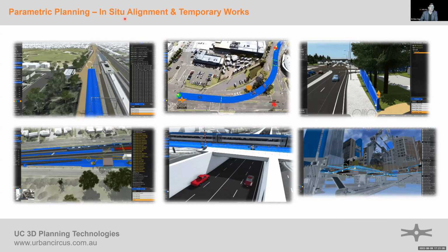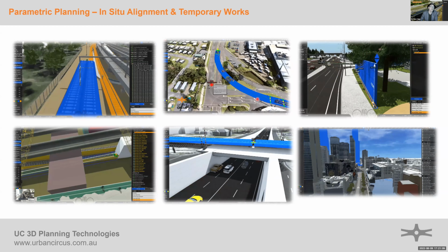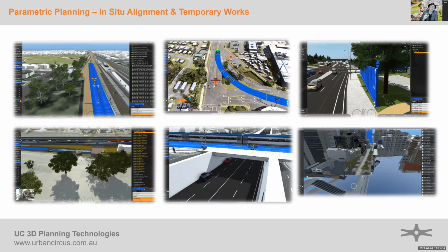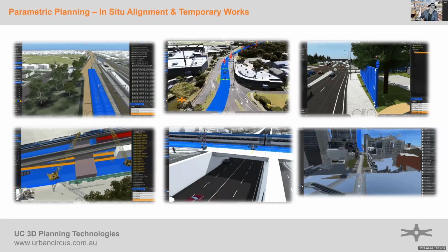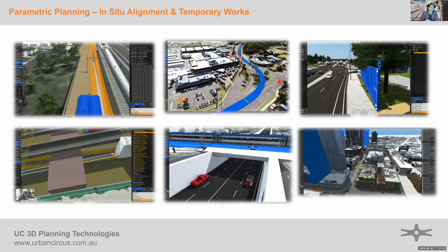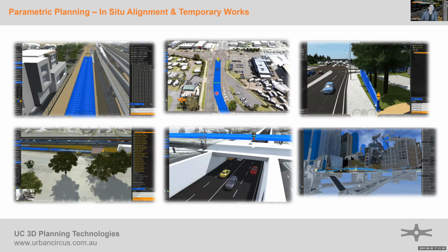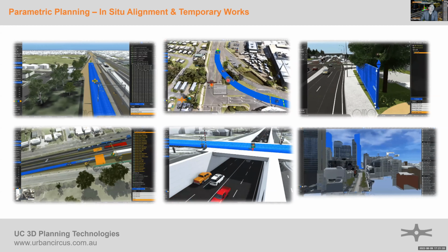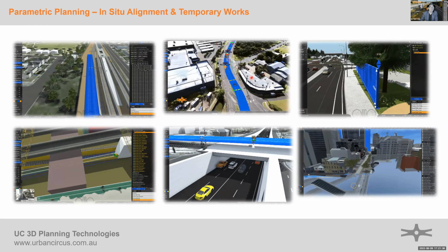This one here in the middle is a photogrammetric model of a place called the Sunshine Coast, very nice place. What we're doing here is testing out light rail alignment routes, so it's trams, okay? And all these conditions have vertical and horizontal curvature. That's very important based on the speeds. And so basically where these things are red, what I've done is programmed in the top 10 civil engineering conditions that are required to comply to build something like this.